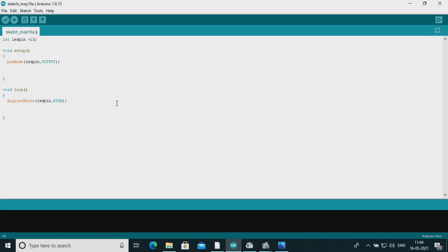Then we will provide some delay. Why are we sending delay? I'll just tell you. Delay 1000. Here the delays are represented in milliseconds. So that's why I'm writing 1000 milliseconds. 1000 milliseconds means 1 second itself.